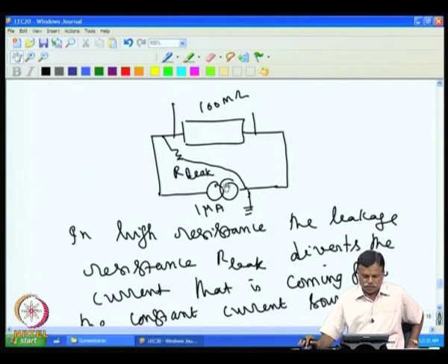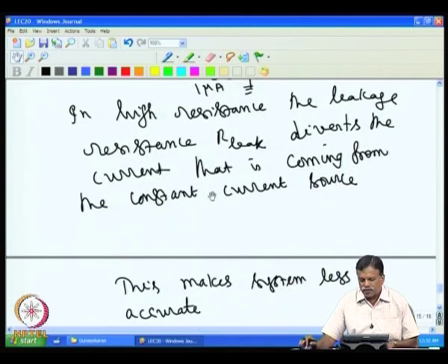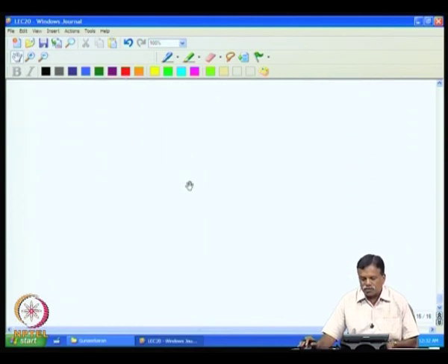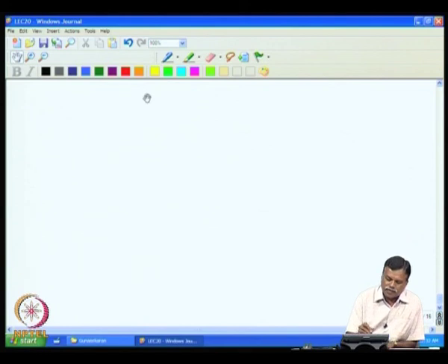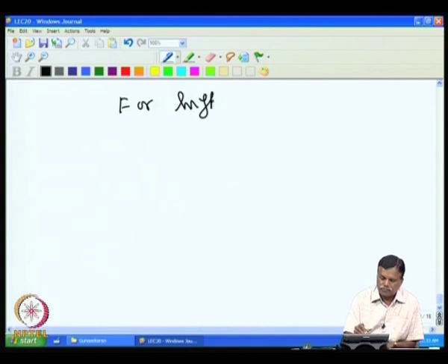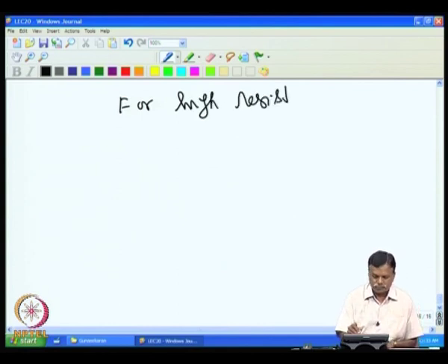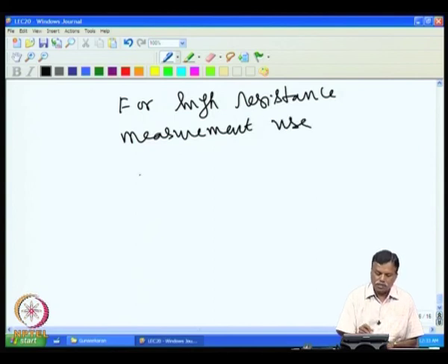because we had seen that for making a measurement for low resistance we can use a 4 probe method, and for intermediate resistance level also we can use a 4 probe method, but the 4 probe method cannot be used for high resistance measurement because of the leakage current. Now, for high resistance measurement one can use the so called ratio transformer bridge. Use ratio transformer bridge.